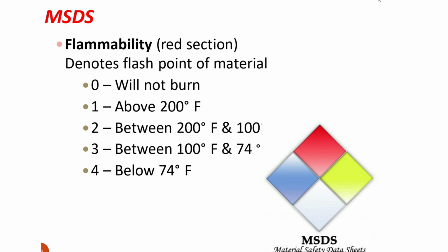Flammability, red section, denotes flash point of material. 0. Will not burn. 1. Above 200 degrees Fahrenheit. 2. Between 200 degrees Fahrenheit and 100 degrees Fahrenheit. 3. Between 100 degrees Fahrenheit and 74 degrees Fahrenheit. 4. Below 74 degrees Fahrenheit.